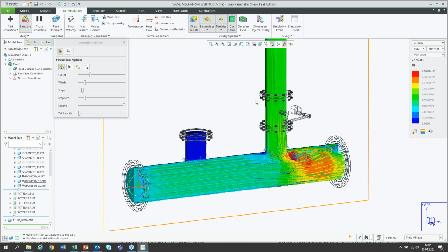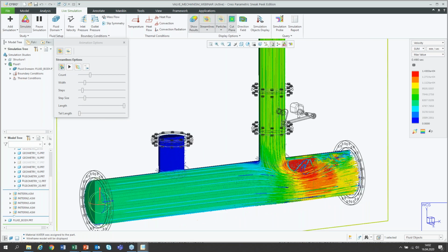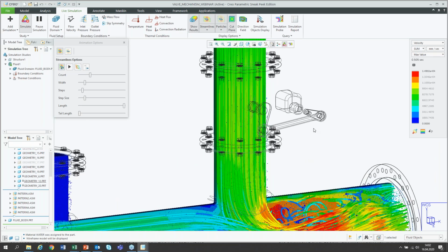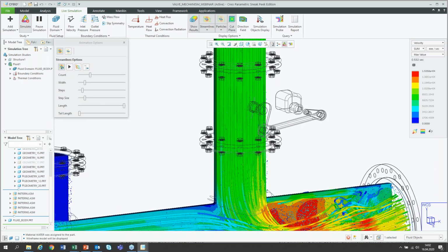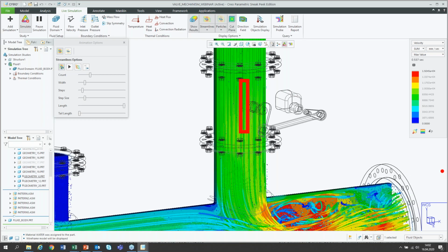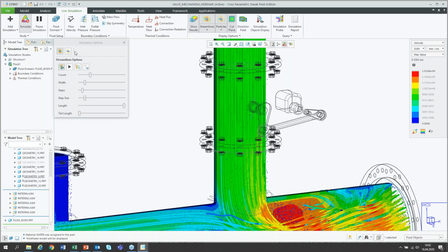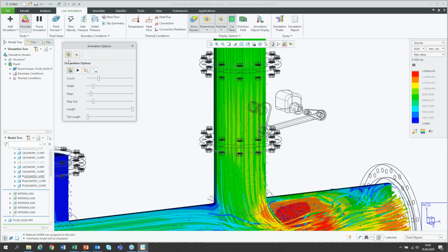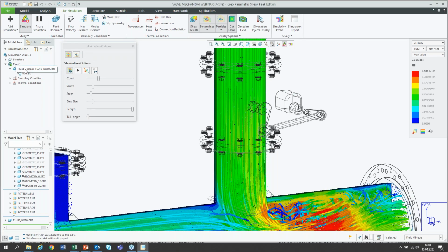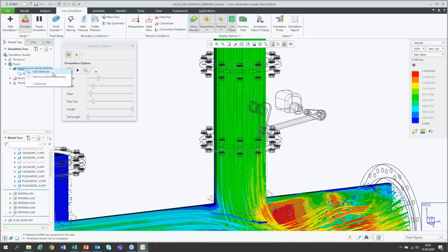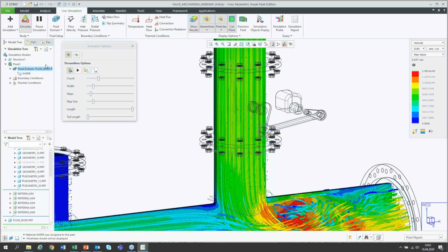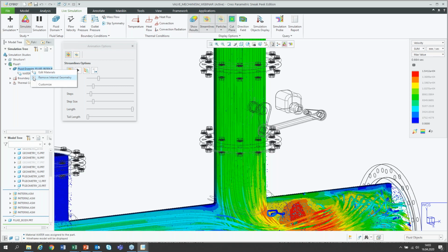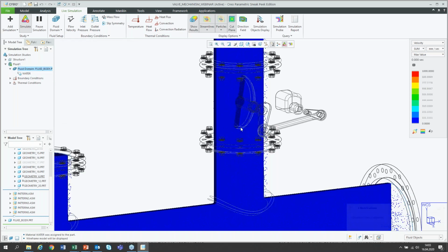And I'd like to take into account my valve here. You see, nothing happens if I'm changing the valve here. And right now the valve has, let's say, that direction. Therefore, I want to cut out the valve of my fluid body. Pressing the right mouse button here, I want to remove that. That means with the red crosshatch here, by activating remove geometry, you'll see the influence on that one.